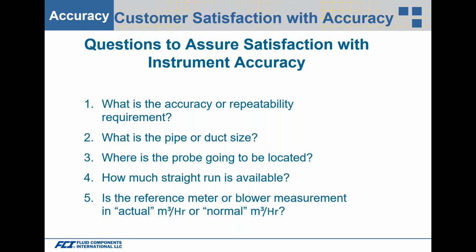Where is the probe going to be located? How much upstream and downstream straight run is available? Do we have elbows? Do we have gate valves? What is the disturbance upstream and downstream? And how far are they located from where the meter should be installed?